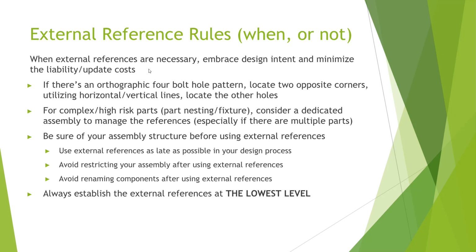External references are necessary, but at least recognize design intent and make sure you're doing it with the least amount of risk. For example, if there's an orthographic bolt hole pattern, so how many of you take a Destaco clamp, put it in your design, edit the part, drop 4 holes in that Destaco clamp to hold it in place with external references, right? Who does that? Okay, when that Destaco clamp changes, because it always does, how many errors do you have?